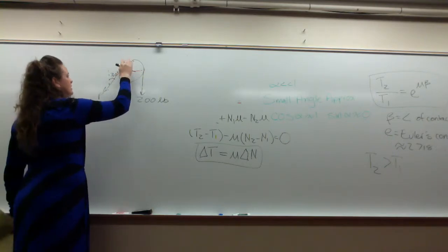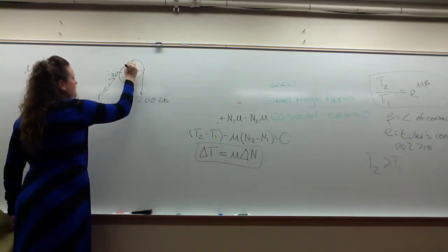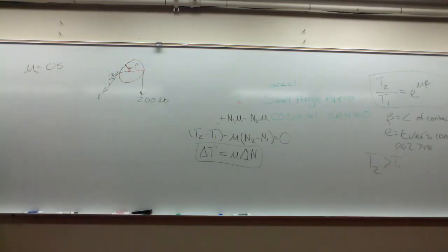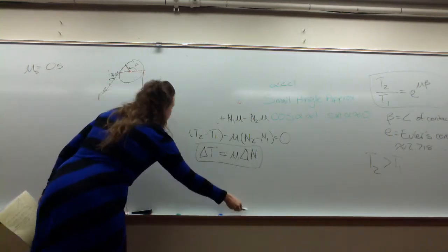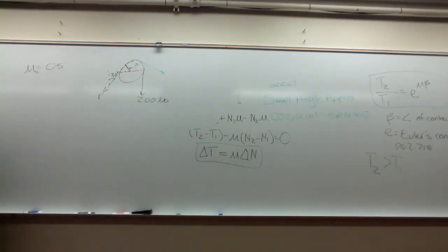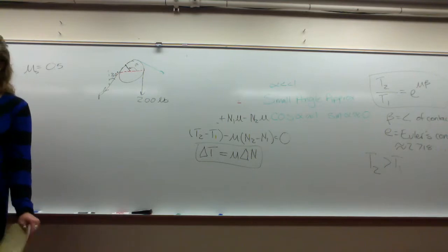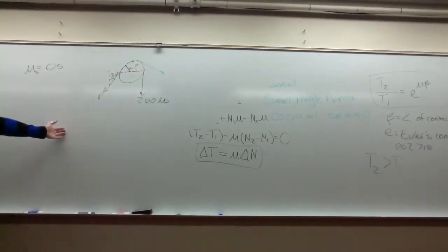Okay, so your guess is right, that our point of contact is 150 degrees. 30 is a fine guess, but look at the problem. If we had a contact angle of 30 degrees, there would need to be some tension that would make an acute angle. And that, mechanically speaking, wouldn't maintain equilibrium.